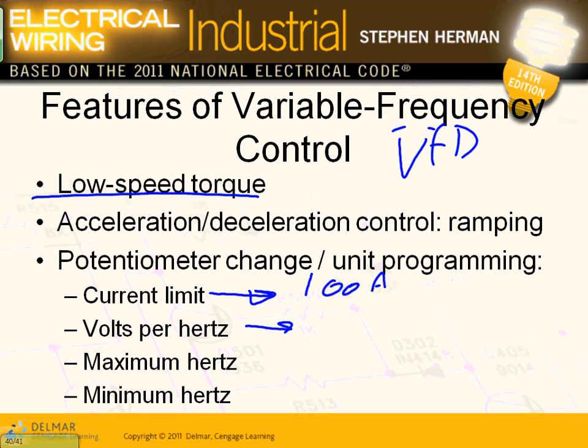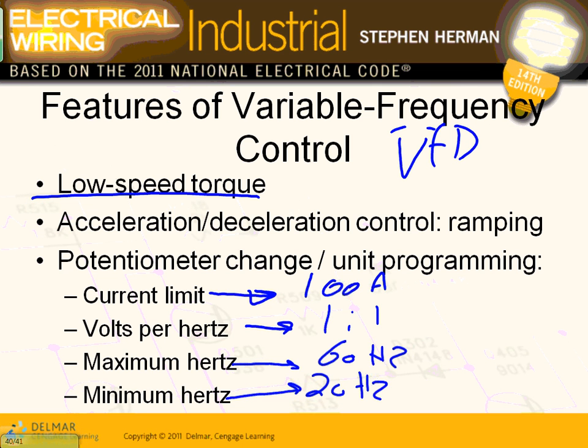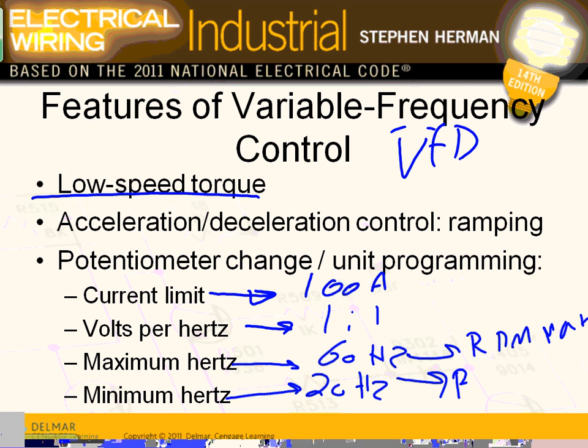1-to-1 ratio. What's your maximum frequency? I'm going to use a maximum frequency of 60 hertz. And what's my minimum frequency? Minimum frequency, how low you want the motor to run, how fast you want the motor to run. I want to put 20 hertz here. So these translate to RPM max, and this is RPM min.